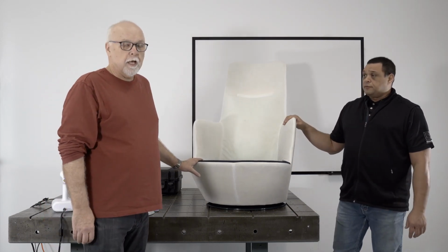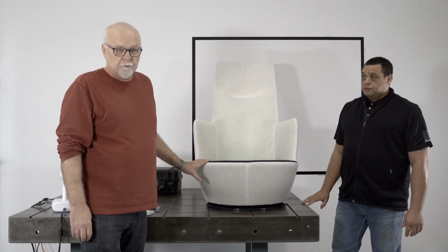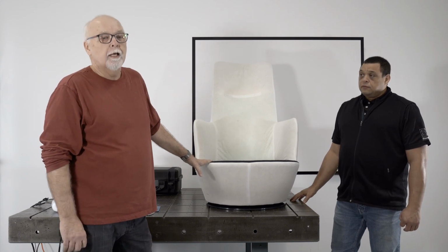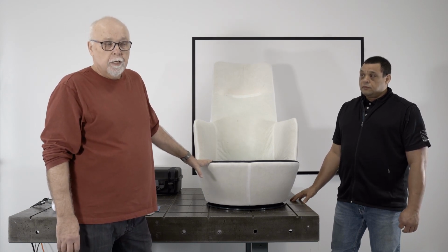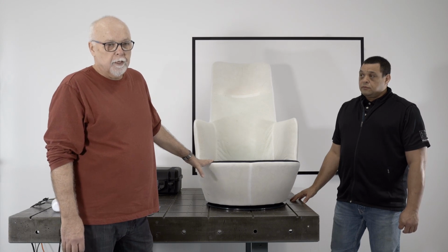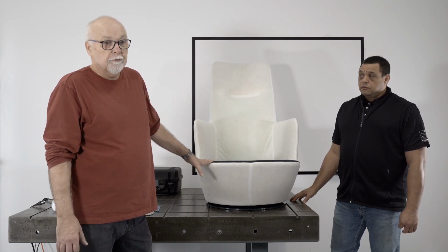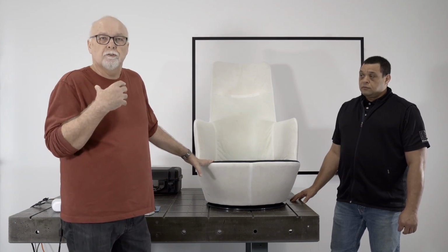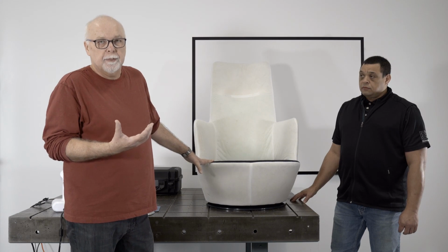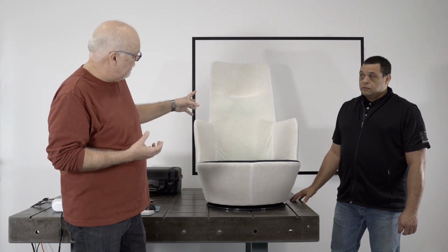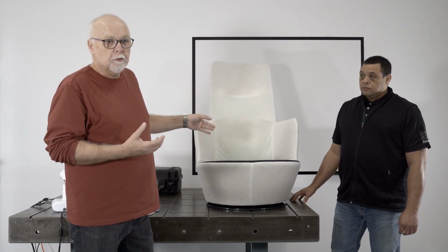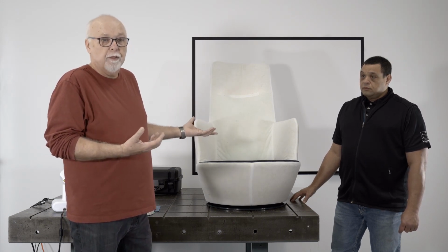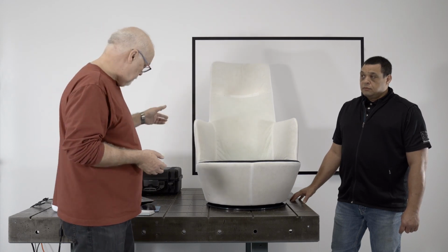Okay, our scanner can scan on 3 things: texture, color if you like, geometry, and it can also scan on targets. Geometry has to be a reasonable amount of interesting geometry. If I try to scan, say, a soccer ball, it's perfectly round, it looks the same from any direction. I could probably scan this without targets, but your life will be so much easier if you do it with targets, so why bother? So we're going to put targets on this chair.